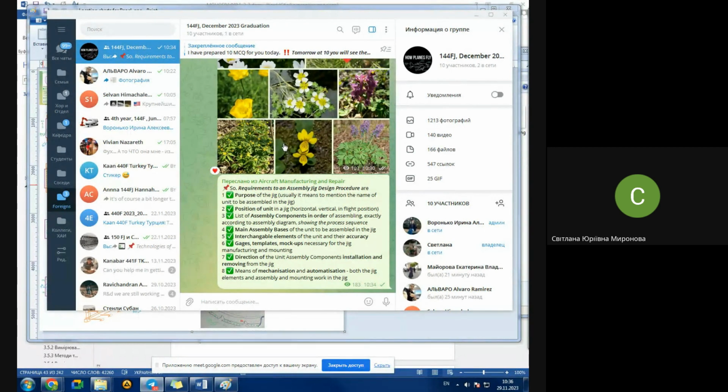Here you are explaining accuracy that you have calculated in the previous items in your virtual work. And literally you need to mention here which locators you need in this jig. So what you write in item number 5 is literally a list of locators and the accuracy that these locators should result in.